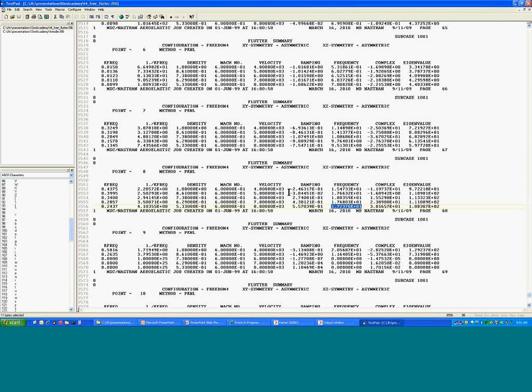More importantly, what we see is the damping. It was stable, with what's called negative damping at 4,000 and 5,000 inches per second, and then at 6,000 inches per second we had positive damping. So I can't tell you at this point what the flutter velocity is, but we enter a flutter event somewhere between 5,000 and 6,000 inches per second.